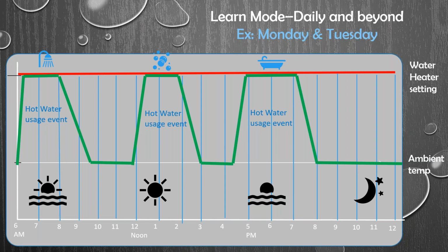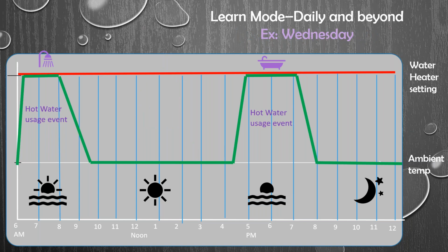Smart plug has a 7-day calendar built into it. So let's say on Wednesday, there is nobody home doing laundry in the middle of the day. And so therefore that event is not recorded. So now we're looking at a very, very small amount of runtime, actual power consumption of the circulator itself that's going to run your DHW recirc system.